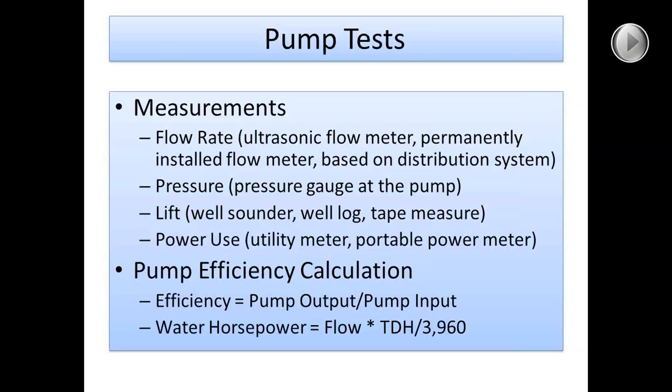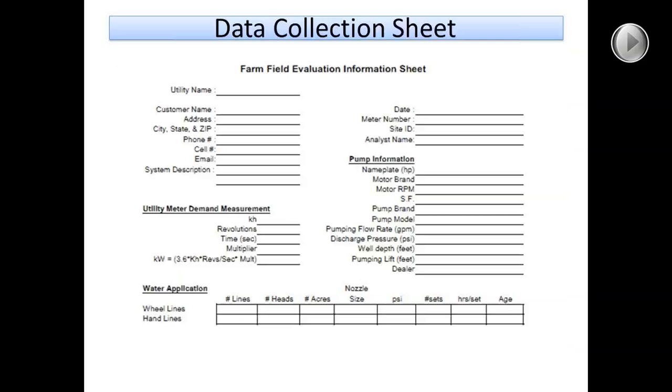Power use, as part of each pump test, we measure power use. Sometimes we can use a utility meter to make that measurement. On my sheet, I didn't really cover this. I'm going to go back really quick. I kind of skipped that part on my data collection sheet. Right here, we can measure the power use using the utility meter.